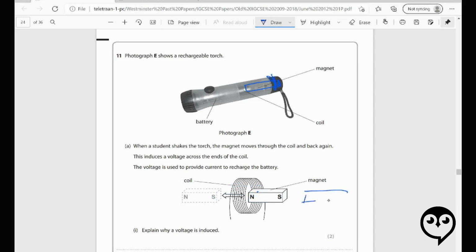If I've got a magnet way over here, some field lines will not go through that coil. But if I've moved that magnet closer, now you can see all the field lines, even when they go out and around, are going to go through that coil. So the closer you are, the stronger the flux going through there, and then when it's changing, this is what induces that voltage. And this is how we are charging the battery.